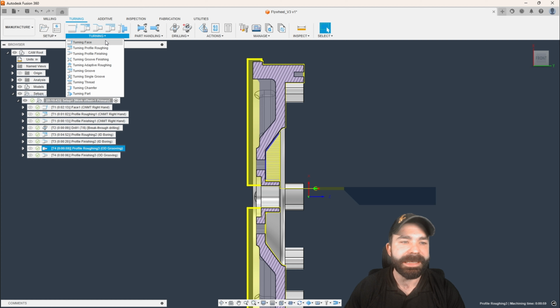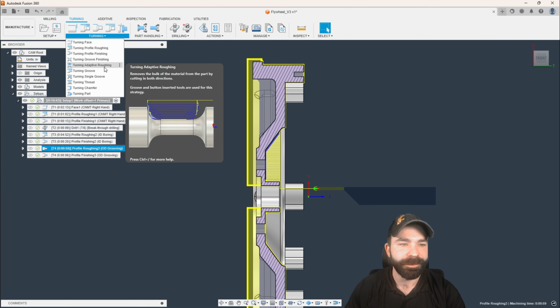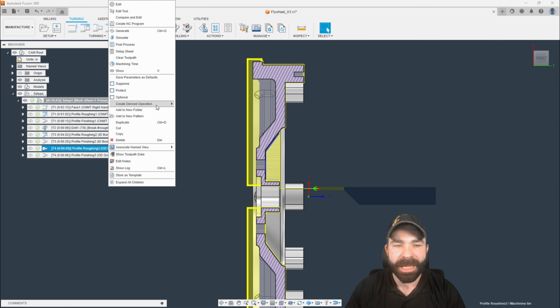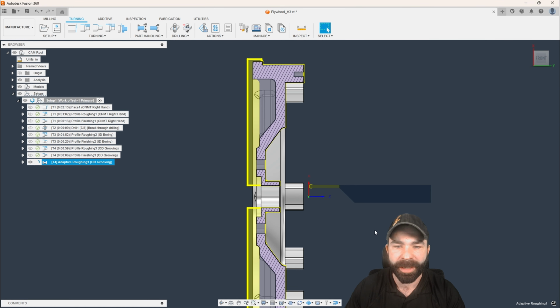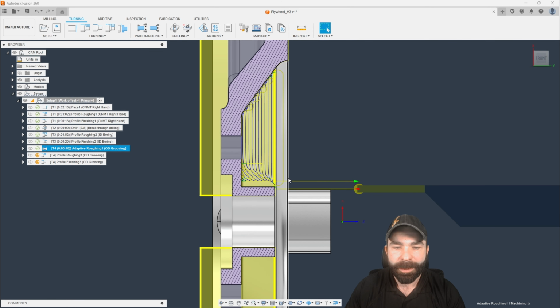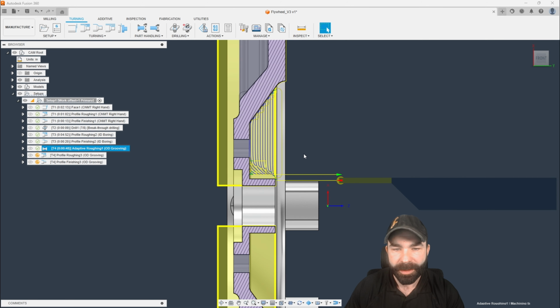If you guys wanted to, by all means, instead of using that straight on roughing approach as you see here, there is the ability to now try out the actual adaptive kind of roughing strategy. And I would recommend giving it a go because it can make a very dramatic difference on how you are getting these parts roughed out and cleaned out at the end of the day. Because of rest machining and everything, I'm going to drag this up and regenerate it up here. But now what you're seeing is more of an adaptive approach, and we're also working inside and outside versus front to back, right?